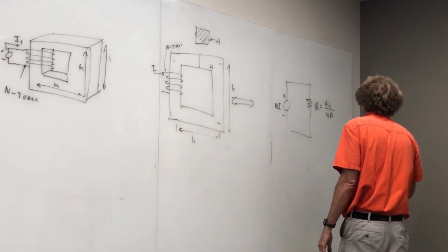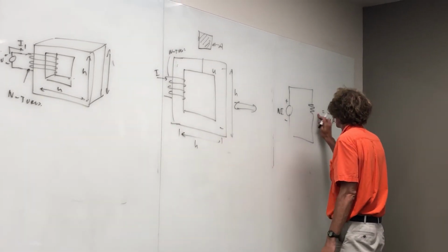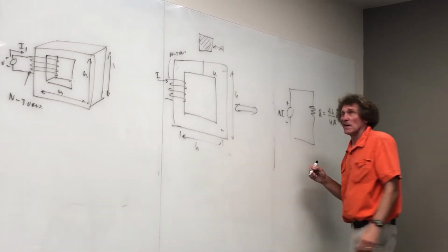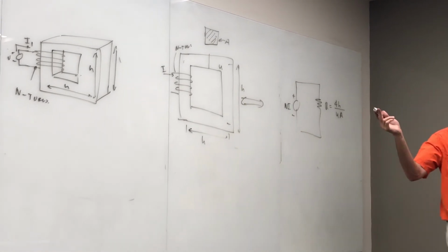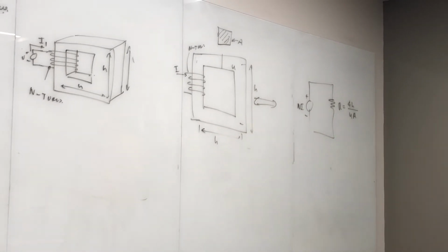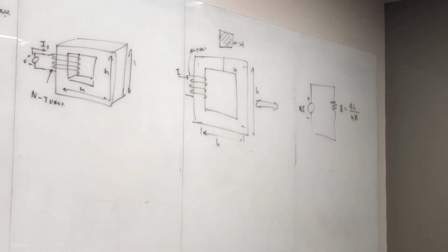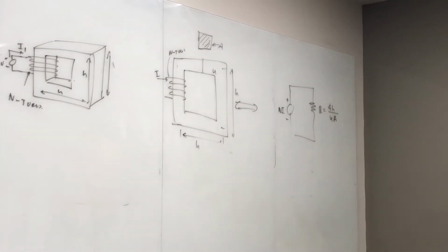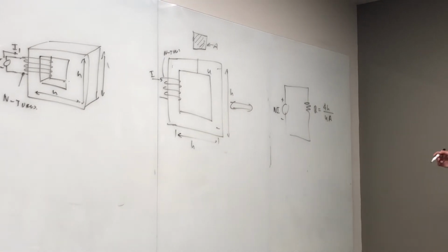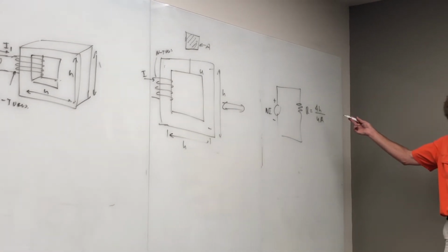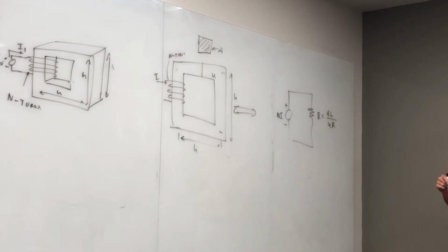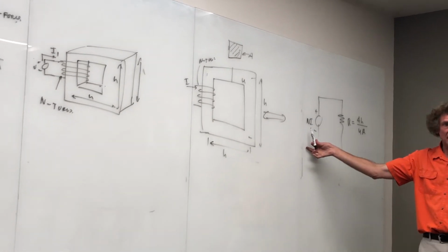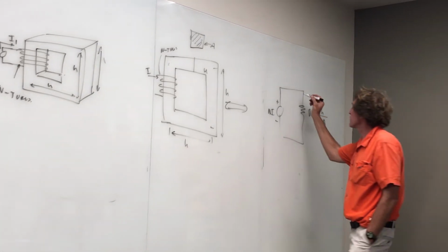And actually, the units of reluctance, I don't even know. Actually, I know, but it would be amp turns per Weber, but there's another unit for it, but I don't even worry about that. Anyway, I'm going to tell you that's the reluctance, right? And that's like resistance. This is like voltage. Follow me, guys? So what would the current flow be?